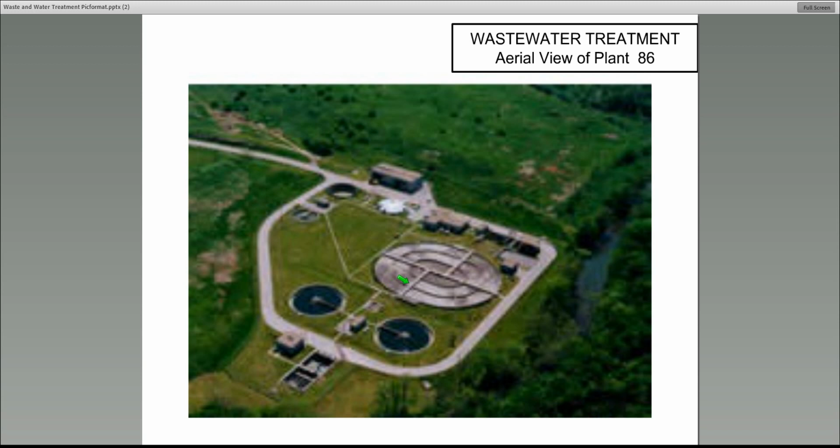So basically, instead of having everything in a horizontal line that would take up a lot of room, it's condensed in a very small area where you have the settling tank and the aeration tanks in that same area. The clarifiers, you have to have two clarifiers. So here's one clarifier, here's the other clarifier. The chlorinator would be here. The chlorine is kept in an explosion-proof building here.